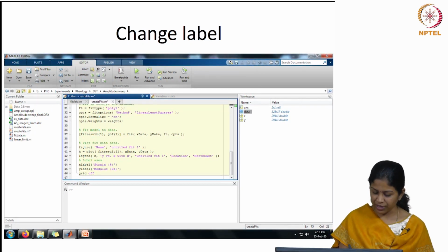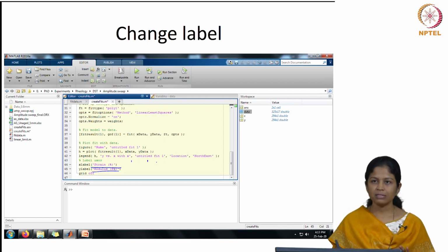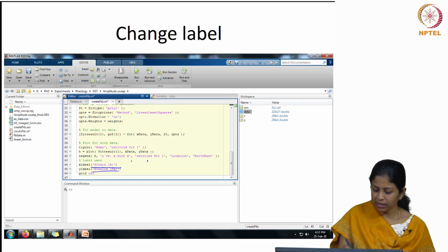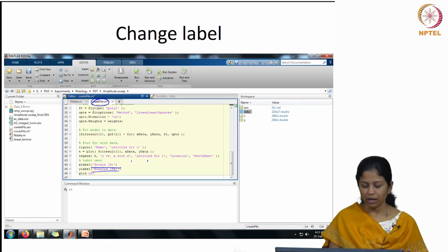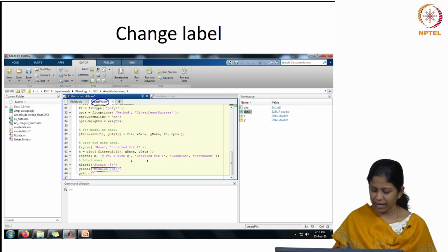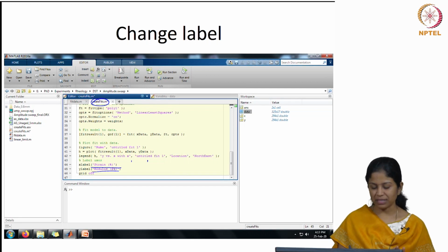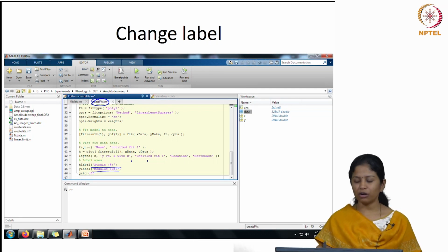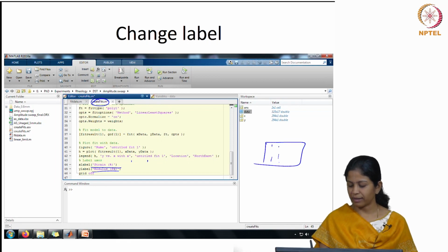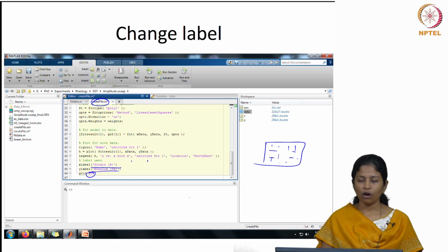Now, we will go to this and change x as strain in percentage and y as modulus in Pascal. Whenever you write a text or a string, you have to put it within single quotes. I am doing this in the create fits function file. You change x label and y label to whatever name we want. Here we are giving strain in percentage for x label and modulus in Pascal for your y label, and I do not want those grid lines which are there in the background. I want to switch off those grid lines. So, here I give grid as off, right.